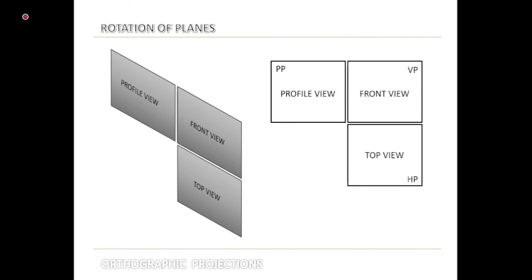Tell me. Sir, where will the back view come? You do not need the back view. From these three views, it will be quite clear to you. Sir, if the profile is unsymmetrical? In that case, you need to draw it. So the back view will come above the front view. Sir, there it will come the bottom view, no? Yes, that will be the bottom view of this. But sir, sorry, back view. Yes, it will come.